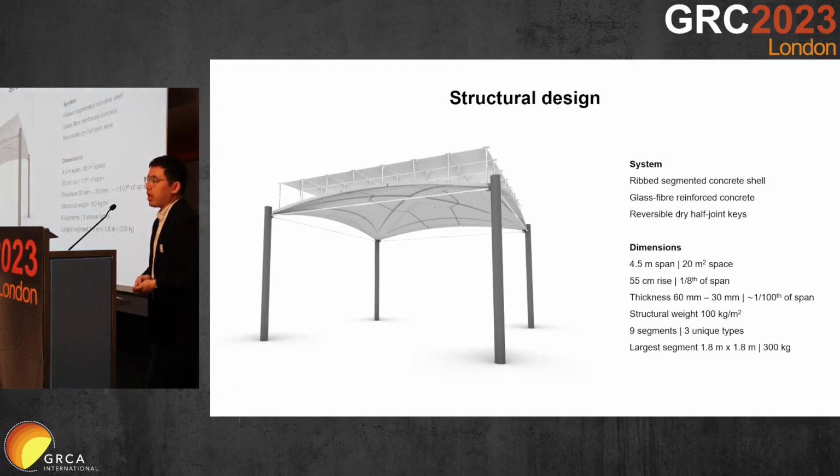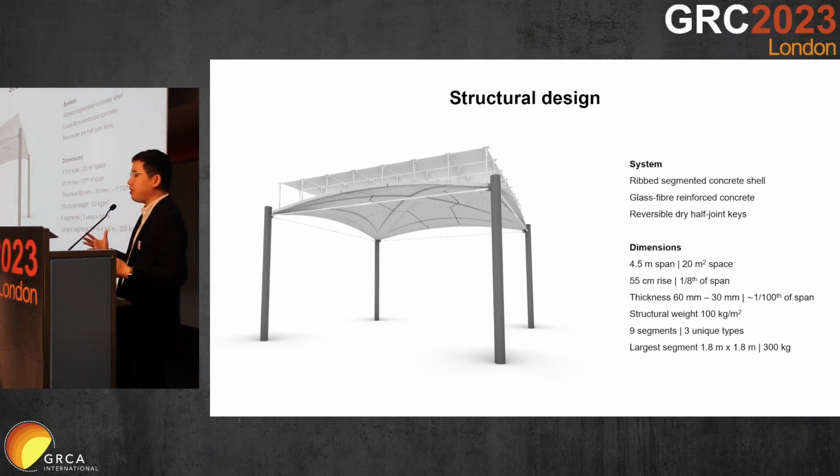So with this fabrication process, we attempted to demonstrate its efficacy by creating a thin shell concrete flooring system. This is shown on the left here, and it consists of a doubly curved shell, which was form found, that has ribs on the bottom surface. It's going to be fabricated using glass fiber reinforced concrete, and it consists of 9 segments, which are thrusting upon each other and whose horizontal stresses and horizontal thrust is resolved using these steel ties.